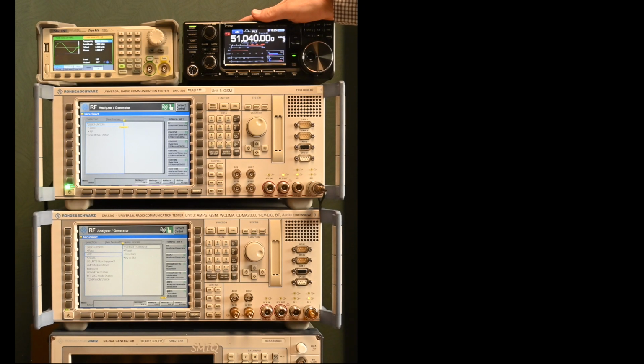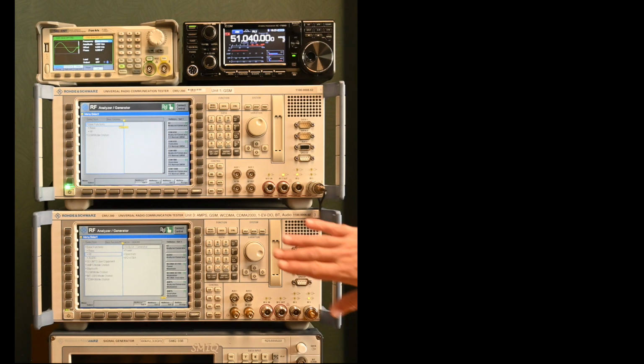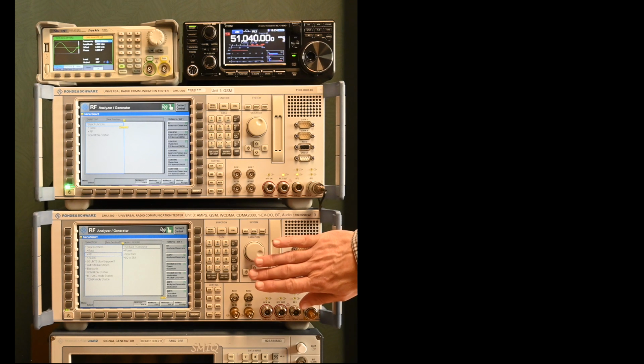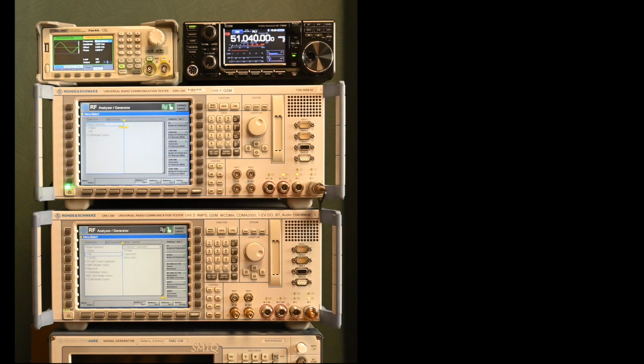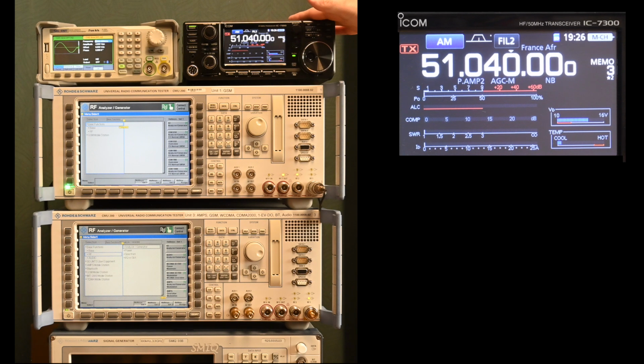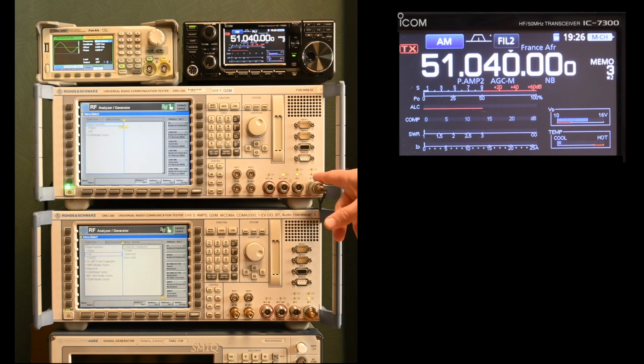Now, here you see our setup for the wideband power level measurement. We have a 2 watt maximum unit and a 50 watt unit, and we'll be starting with that one. Of course, since we also want to test the 50 watts, we have a signal generator here. Actually, we have a ham radio that can deliver all the way up to 100 watts of power. Since it is loaded by 50 ohms, the input impedance here is 50 ohms, there's a dummy load inside, so it's able to deliver its full power into that.